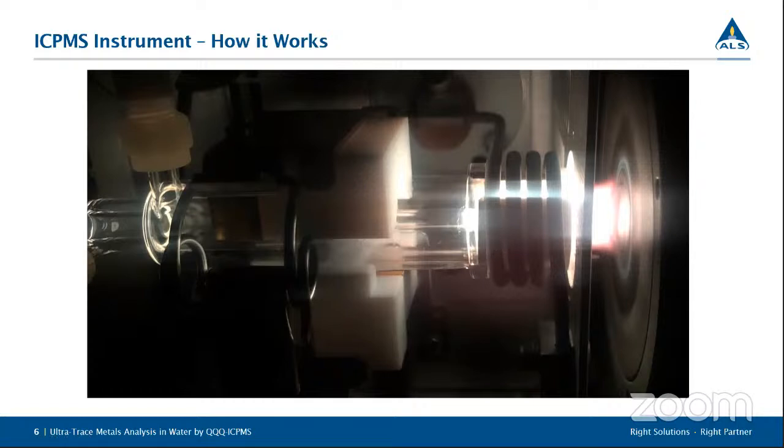As you might imagine, the instrument requires a lot of argon gas. It's flowing at about 15 liters a minute. To put that in perspective, your standard T-size cylinder, about 9 inches wide and 55 inches tall, charged to about 3,000 psi, would only give you about 6 hours of runtime. So you need a bulk source of argon in order to run these instruments.